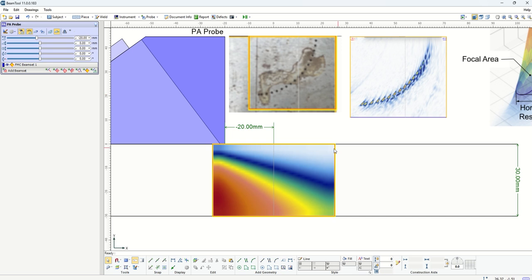Here you notice that when we are at the bottom left, both the size and the shape of this point indication is closer to the holes, and its intensity or sensitivity is higher. Exactly as you see here, you get much closer to the actual size of these holes and high intensity. But as we move along this arc up to here, we start to get a blurred indication, basically an elongated arc, and low sensitivity value. And that's exactly what you can see here.